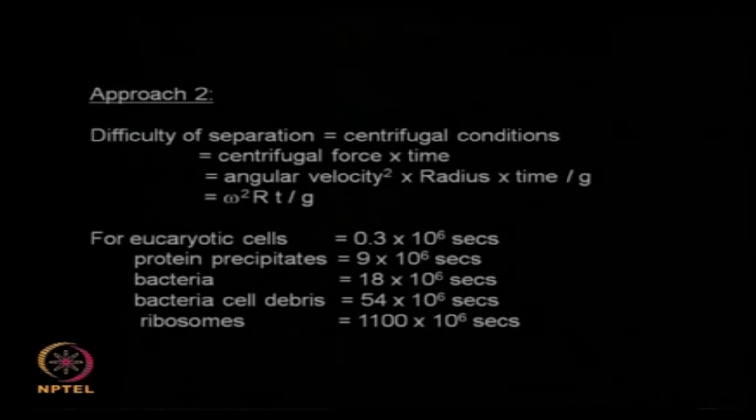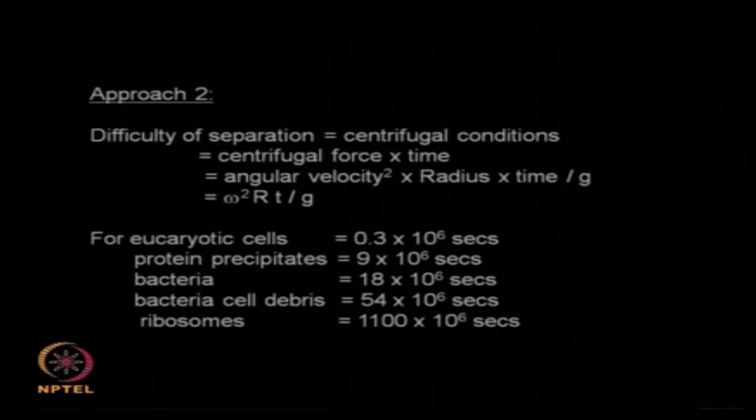That means throughput is directly proportional to hardware parameters. So throughput in centrifuge 1 divided by throughput in centrifuge 2 will be equal to hardware parameters in centrifuge 1 divided by the hardware parameters in centrifuge 2. So, if I know the details in small scale, I can estimate the details for a large scale.